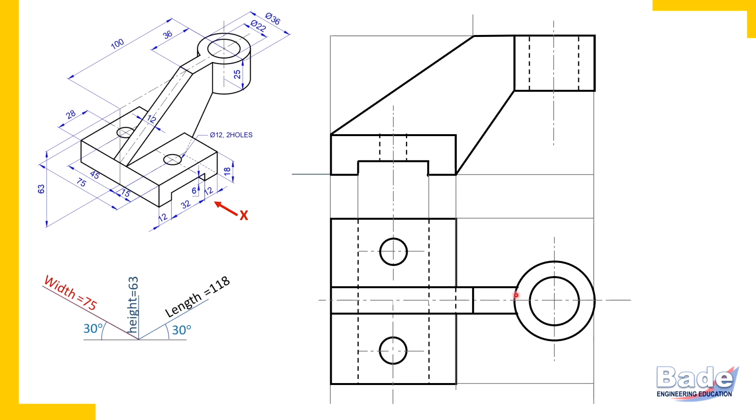Now here watch. We should trim this portion. Because these surfaces are in one single plane. That's okay. But one very important thing. Similar circular edge is at the base of the cylinder also. Here it is. And this circular edge is still there, but it is hidden from top. So its some portion will appear here. So don't forget to draw these hidden lines. This hidden line here, that is actually base edge of the cylinder, bottom edge of the cylinder, which is still there.